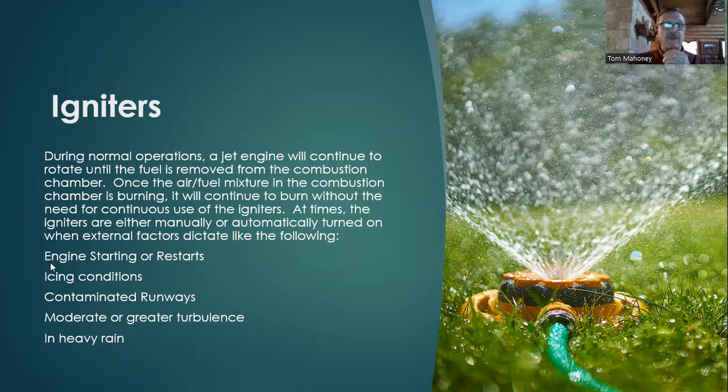Obviously, we're going to have them ignited during engine starts or restarts, because if the engine is not running, we're not generating any air-fuel mixture, so nothing can burn. So we've got to get that stuff rotating first and then burning, and we do it with the igniters.